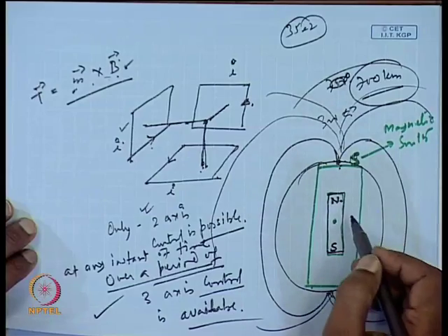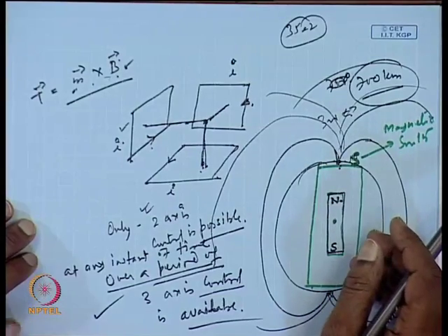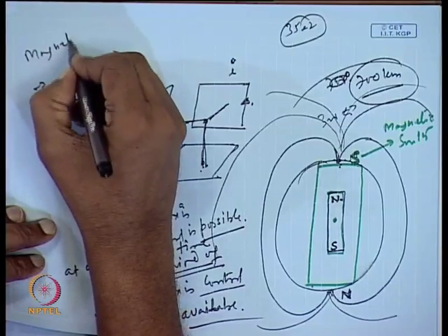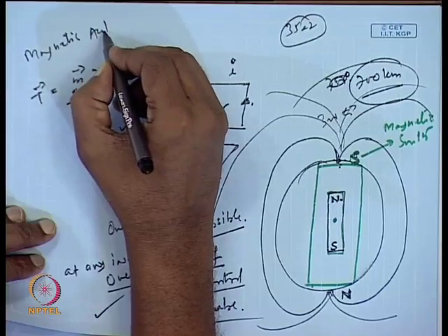In that case it can be utilized, and it is low in cost, easy to design, and also reliable. Active control can also be done using this, but a few limitations are there. If the satellite is rotating at a very high speed, it is not feasible to use these magnetic actuators, because they can control the satellite only at lower angular velocities, at lower rotational rates. So, this is our description of magnetic actuator control.